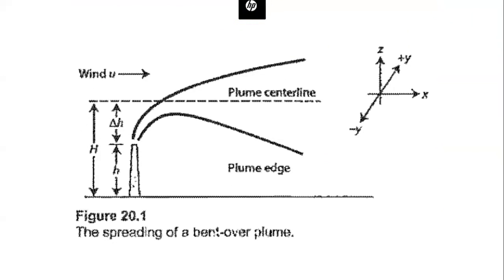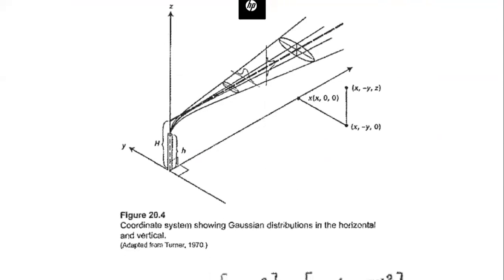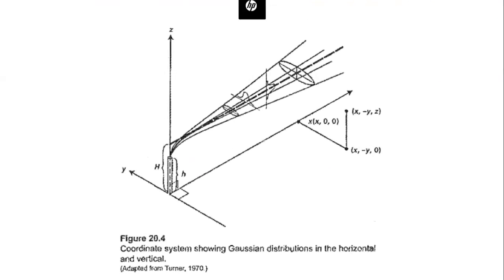If you had taken the 2601, I think you already did some calculation on this. So here we'll just briefly go through the design methods, okay? Basically, when the plume dissipates, the scale of it, basically the width and the height, is also going to increase. So people created a Gaussian model to predict the transport of the plume.